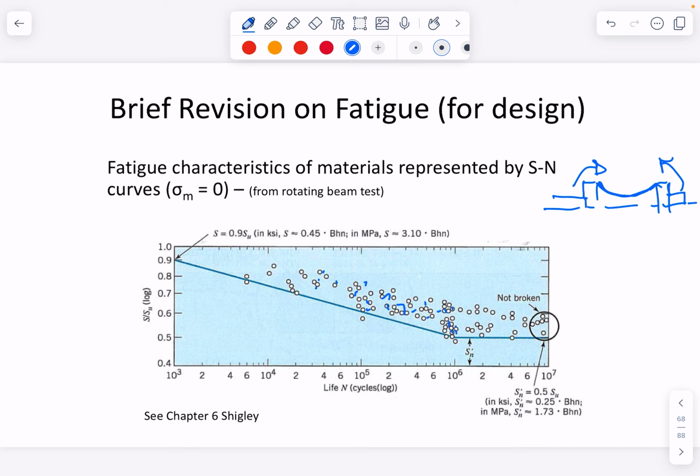life. Okay, and if you're looking at a carbon steel, and by that I really mean any of the steels that are not stainless or that sort of thing, you will end up with a fatigue life curve that goes from 1,000 cycles to 1,000,000 cycles to 10 million cycles, etc. And there is often a knee point at about 1,000,000 cycles where, as long as you're below that level, you can just keep using it forever and ever. If you happen to be operating at this sort of stress level, then you're likely to be thinking about it breaking at around 20,000 cycles. Okay.